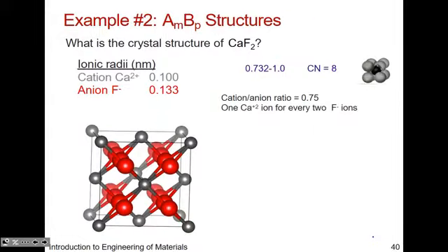Okay. Now, there's a homework problem in homework 1 where it deals with this calcium fluoride or calcium difluoride structure. And what I want to say about this system and relating A to the atomic radius is that you want to see which direction, once again, where the atoms are touching. In this case, where the ions are touching. So here, you want to focus on the cation connecting to the anion here.